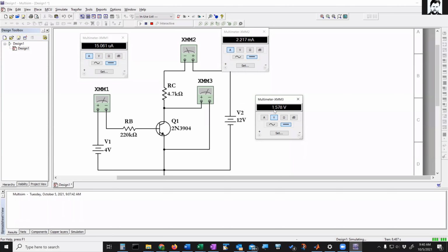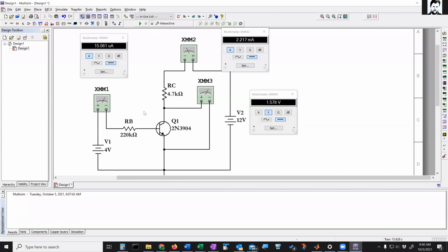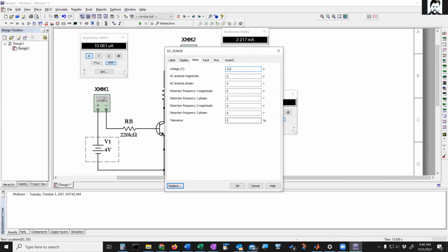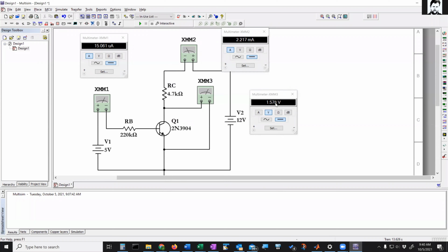The voltage across it is very low. And we know that as the voltage reaches 0 over here, that means it's acting like a closed switch, or that's the saturation mode. So we're getting pretty close to that. You can see the voltage is 1.5 here. Now watch what happens if I increase it to 5. Oops. So it was 1.5. Keep that in mind. Now it drops down to 191 millivolts. So that's 0.2 volts roughly.